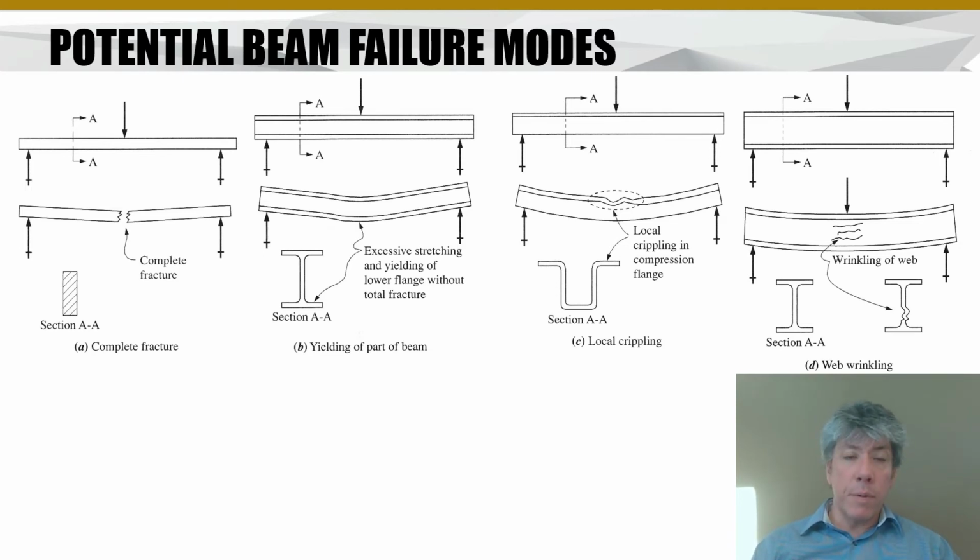The beam also is assumed to be long and narrow, and that is important for this equation derivation. It's just because we can't have variations in the stress from the applied loads. The cross-section has to be uniform, so you can't have a beam where the cross-section is varying along the length of the beam, otherwise again this equation doesn't work. The beam has to not twist, and the beam has to be essentially straight. So we're only talking about very small deflections of the beam. If the beam is deflected a lot, like in that exaggerated picture I had a moment ago, again this equation will be somewhat inaccurate.